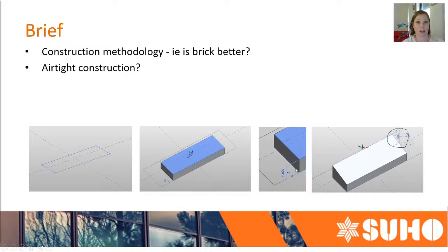And then we start looking at things like, in this case, does it have a boundary wall? Well, we know that can only be 3 metres high. That's our basis on the south, which is not a bad thing, it's the south. On the north, we might want to increase the opportunity to get high level lighting, so we might increase this shape so that we have opportunity for high level windows, or we can really work on that north glazing.